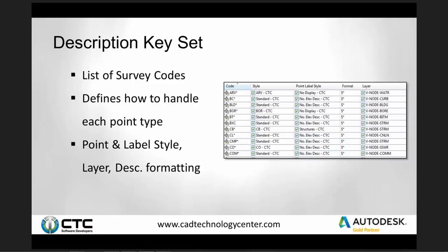So a little more about the description key set. We've got a lot of people attending today, so I'm going to try to provide some background, some intro explanation on some things, but we'll get fairly advanced in topics too, so it should be a little something for everyone. What the description key set is, it's a list of your survey codes, and so this is for existing surveys, topography surveys, and so forth. What codes are being used in the field. We have to list that, and it defines how to handle each point type based on those codes.